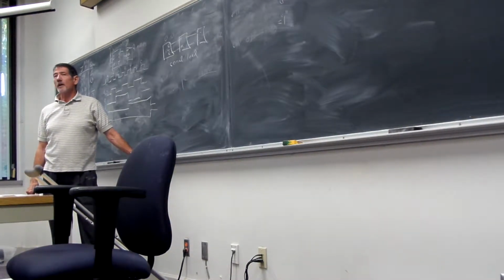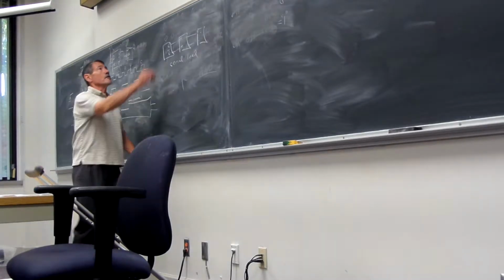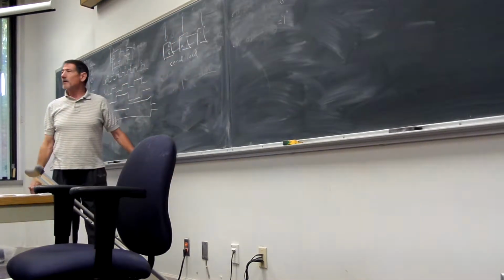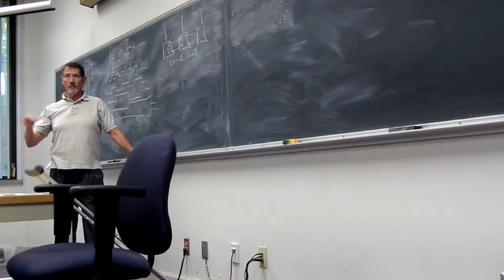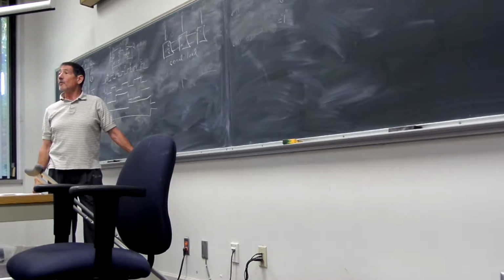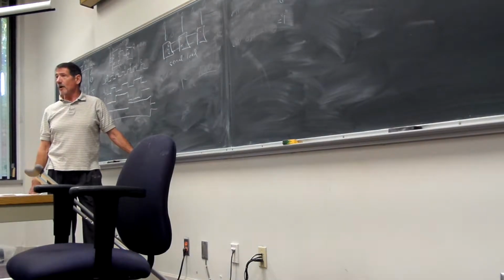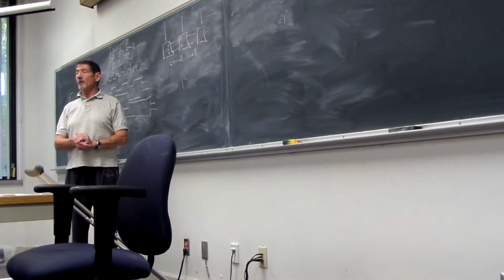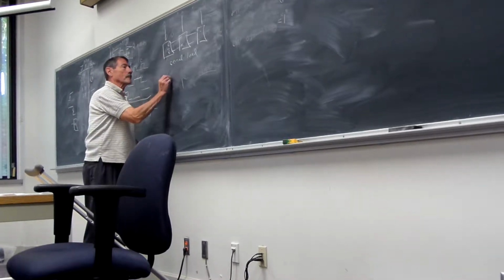There are also ways to just dump everything in one fell swoop, so that there are some of these that we can preload them in parallel. So we give it a command and we say, bam, we're going to make your Q do what we want it to do, either a 0 or 1, and we can do all of them in one fell swoop. So that would be a parallel load.